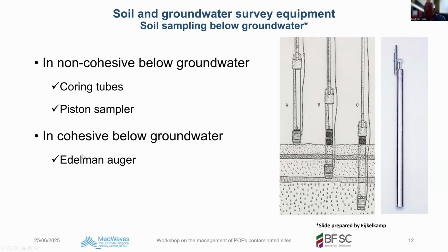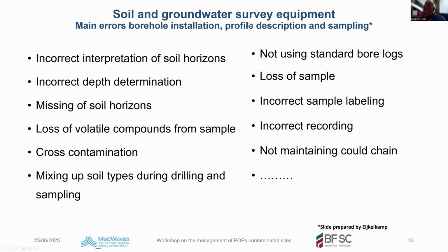In cohesive soil below groundwater, you can use these Edelman augers, which I just showed you in the picture before. Many errors take place during borehole installation, profile description, and soil sampling. I have listed a few here. Incorrect interpretation of soil horizons, incorrect depth determination, not describing missing soil profiles, loss of volatile compounds from